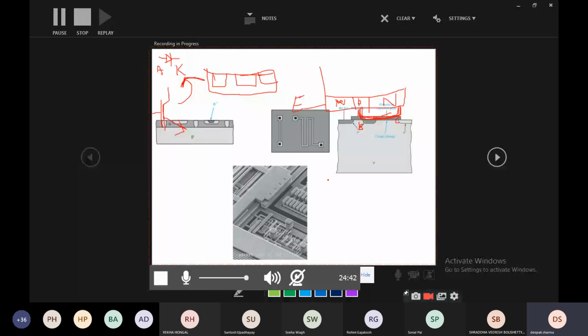So in the process of fabrication, we will follow the same steps. Like here, I said I need two transistors, 1T, 2T, and here I require 1D, right? So I'll not go with that D. I'll go with the T only, and after that, I'll just protect these two transistors, right? And then I'll do this short connection. I'll simply interconnect base and collector, so that only the third transistor gets converted into a diode.